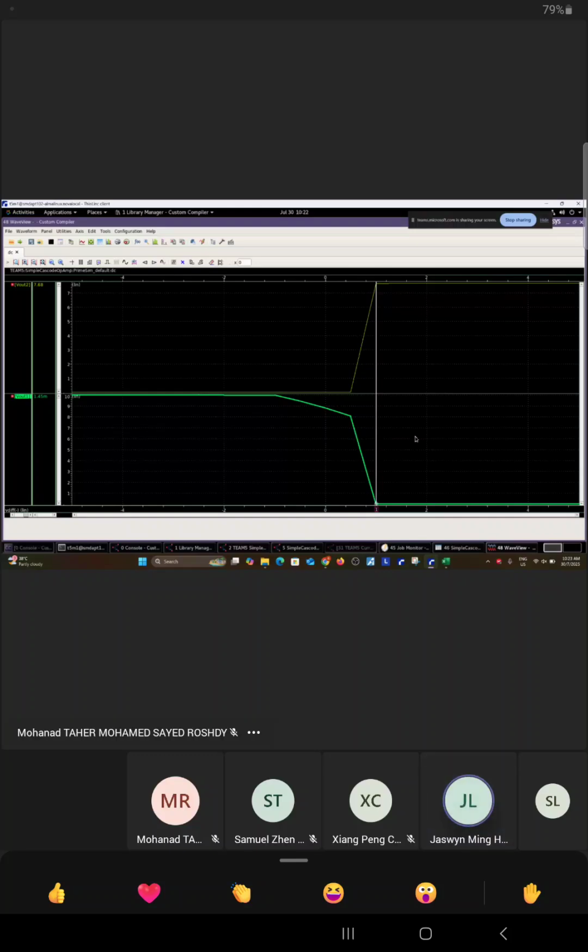0.5 to 1. Let me think. Audio signal, perhaps audio signal, they only swing a bit. How much is it supposed to be, ideally, theoretically? Seriously, I think it still depends on how they want to use it. So this range, of course, the wider it gets, the better. But if you make it wider, usually there's a trade-off. Making it wider means your gain gets smaller and smaller. Yeah, that's the thing, you need to strike a balance.